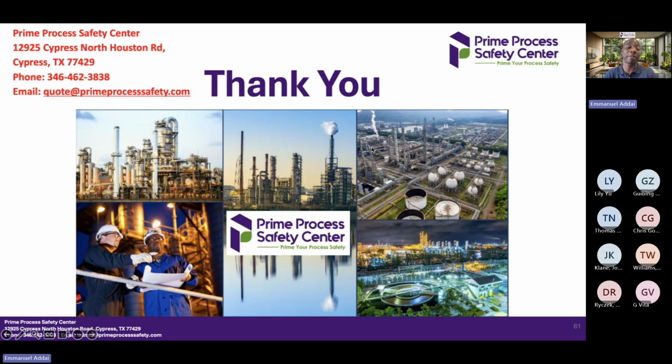If maybe you have several materials, then my colleague is traveling to Florida today for a similar kind of operation where they make spices, where they handle hundreds of materials, and they don't know where to start from. In this case, a hazard assessment needs to be done, and somebody needs to be there to guide the operation on where to actually take the sample. But the most important thing here is the majority of the material being handled. If you have your main product or main reactant, you need to test that material. And sometimes you can also do composition analysis to know what percentage of this material is inside this dust. If at a certain point the material is explosible and at another point it is not, then I have to consider my feed to see what is the most explosive material among the materials that I'm handling there.